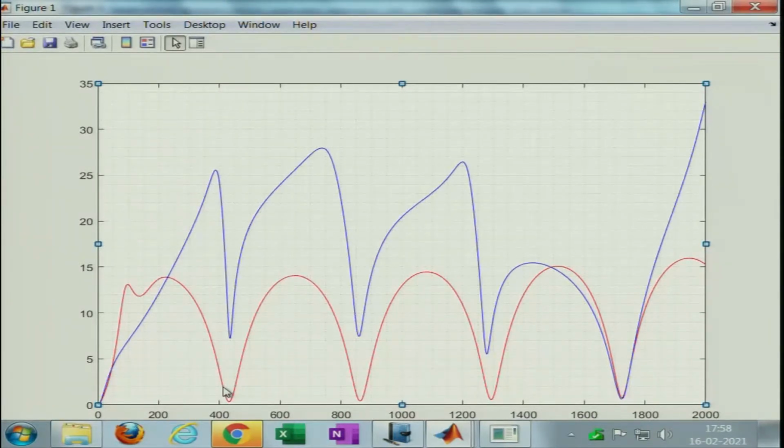And another thing that we must note is that the perforate impedance is a function of many variables, which include hole diameter, thickness, and your mean flow, of course. So they also have to be investigated, and porosity, of course. If we were to do it systematically, we can find a generalized curve fit based on a number of expressions for end corrections as a function of all these parameters. So that will require a lot of trial and error.